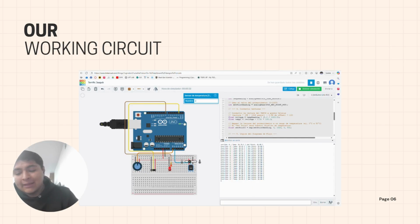Okay, after we combine the simulation, the circuits, and the programming, we have this. As we said before, the potentiometer sets a temperature we need to achieve. The sensor senses if the temperature is already above this or below this. If it's below, it turns on the LED, or the heating system. If not, it will remain turned off. Then, if we turn on the switch, no matter what temperature we set the system to, it will turn on the heating system, or in this case, the LED.